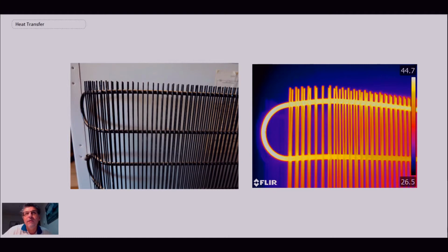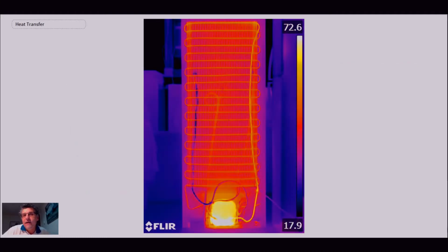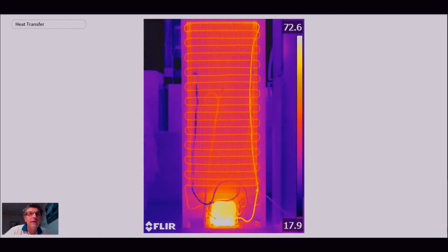And so that's essentially what we're looking at as the refrigerant flows through those coils. And so that would be where you have condensation on the tube side. The condensation is occurring within the tube, and it's going from being a superheated vapor down to the saturation temperature, and then it would go through a phase change, and then you would have a liquid coming out at the bottom. But that is typically the cycle used for any kind of refrigeration system.